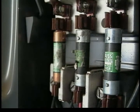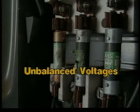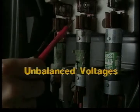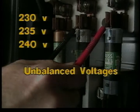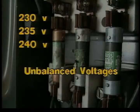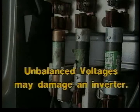Sometimes industrial supply voltages are neither significantly low nor high, but they are unbalanced. In other words, voltages in the three phases are not equal. For example, the voltage in one phase may be 230, one might be 235, and the third one might be 240. In general, the difference between the lowest and highest voltage should be less than 4% of the lowest voltage. The inverter may be damaged if it is operated on unbalanced voltages.